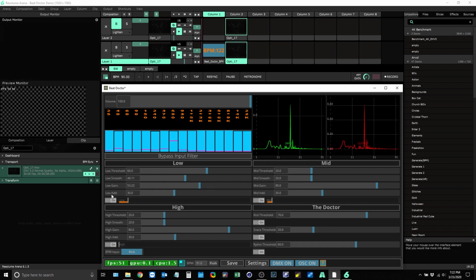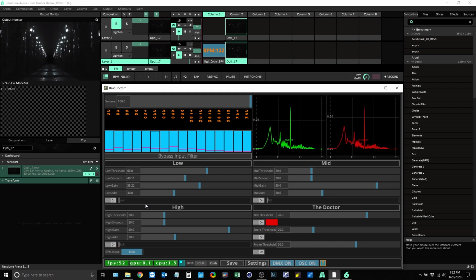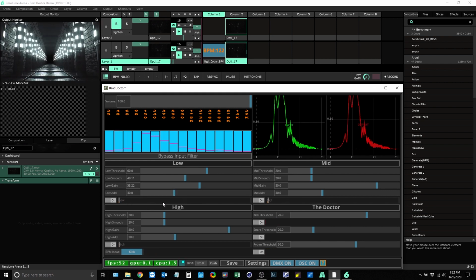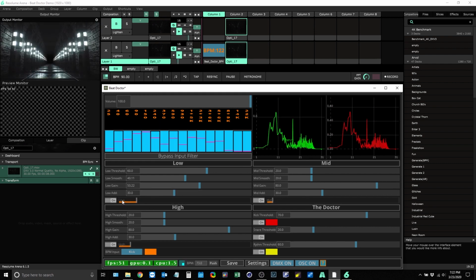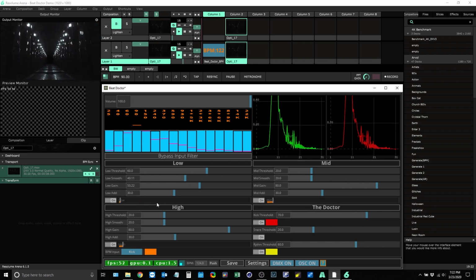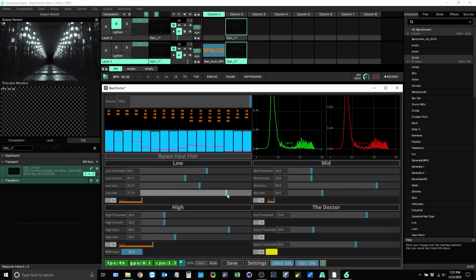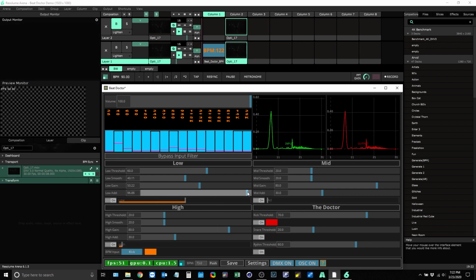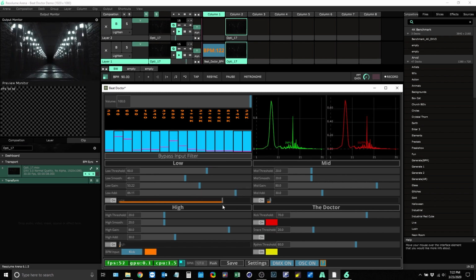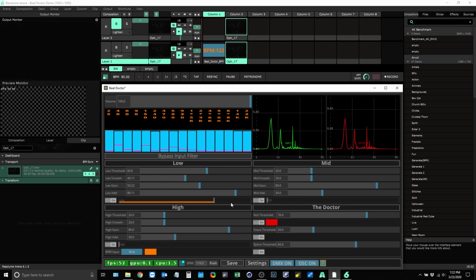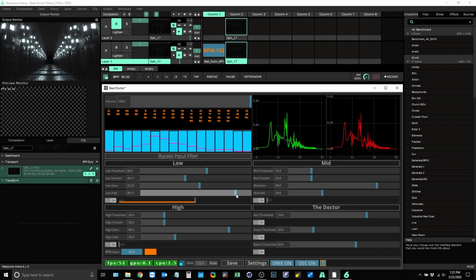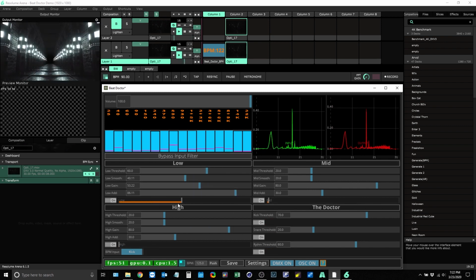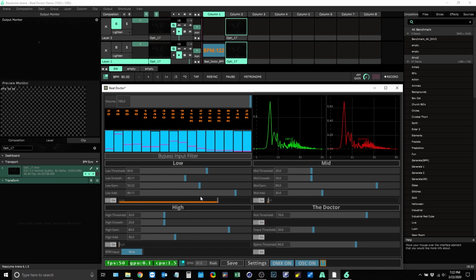And then below that we have our add, and what that does is it even amplifies that gain even more, where if you're only going from maybe like a 0 to a 0.25 range here, as you add this up, it's really going to boost that even higher. So if you feel your lows need to have more dynamic, you want it to output higher up in the numbers, like maybe your 6 to 10 range, crank up your add, and it'll keep all of your settings above, but it just multiplies the amplitude of that.